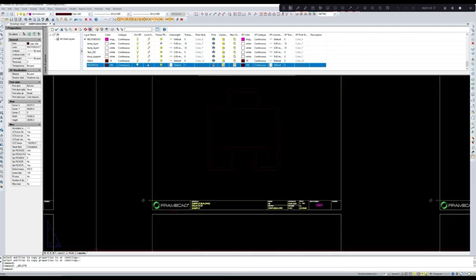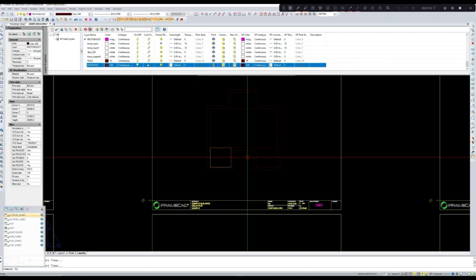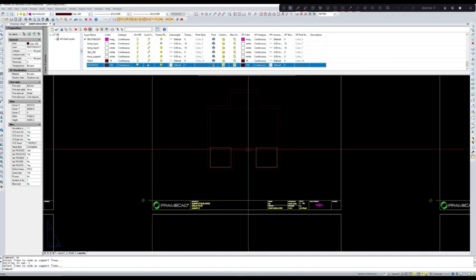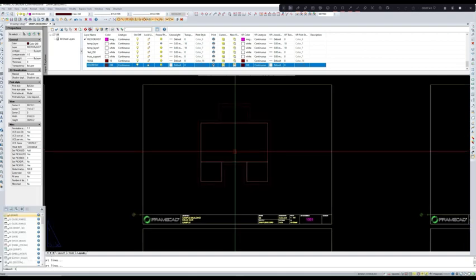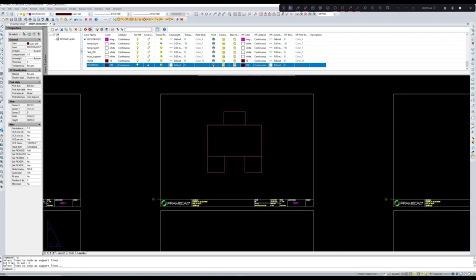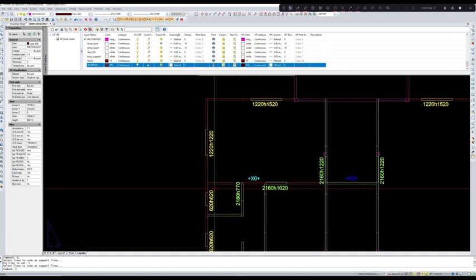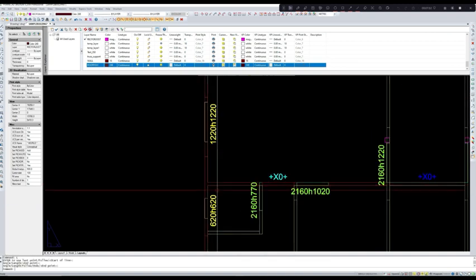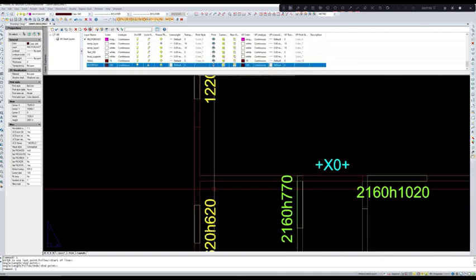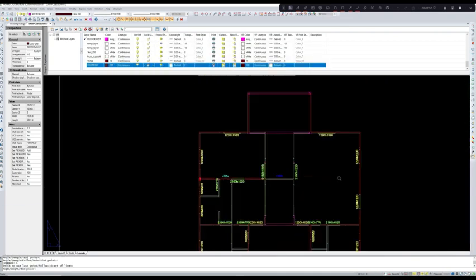SL is the command for support line. So this will be one of our support lines. Enter. This will be SL, enter, then SL, enter, SL, then enter. We have to bring one more support line also. This is the load bearing wall for the trusses. So let us draw a line from its midpoint.